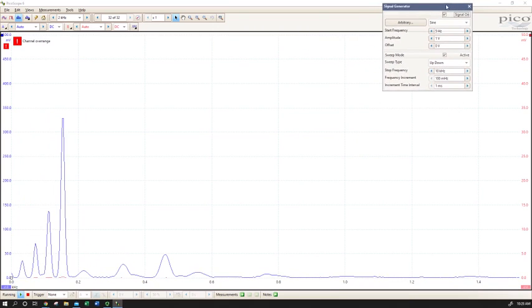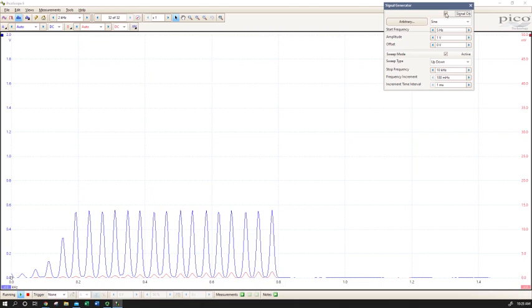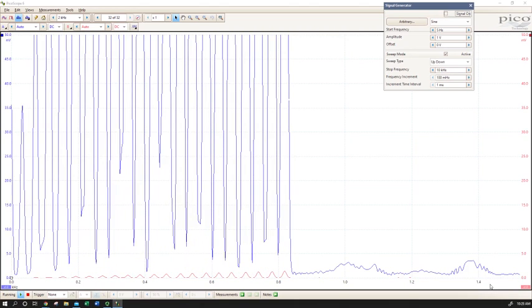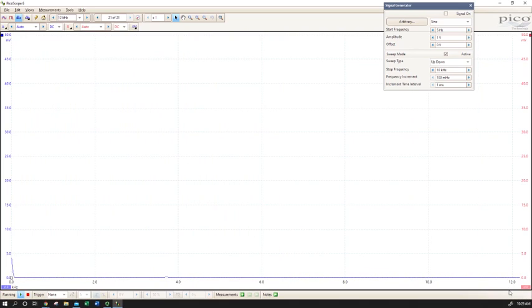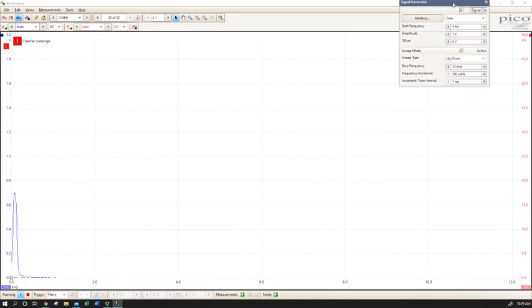I should start collecting. So here we go. We're collecting very small peaks here. Oops. I'm not going to be able to display this very well because I'm only visualizing 2 kilohertz on the x-axis. I want to see all 10. So I better go change this. I'm going to go to a 12 kilohertz full scale X display. So I scaled up my X display. This is like going to a different time base on your scope. So let's try that again.